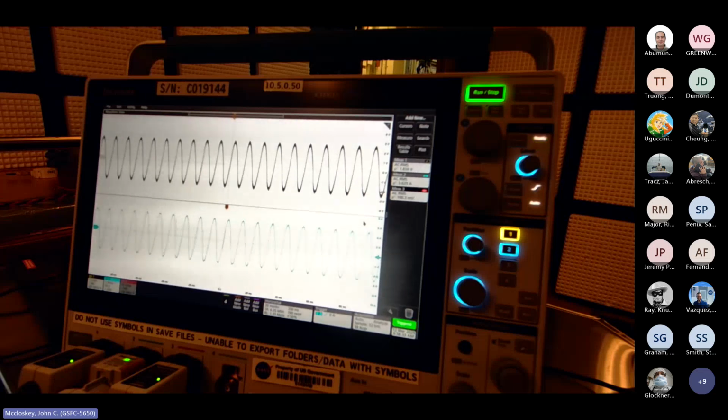And also, in the real test, you're not going to jump from 30 hertz to 100 hertz. The frequency steps down at the low end are 5%, 0.05 F naught. So after 30 hertz, your next frequency step would be 1.05 times 30 or 31.5 hertz. I'm not going to step through all those by hand because it would take you a very long time. But so I'm going to go back to 30 hertz.